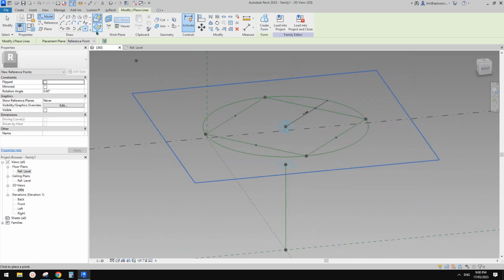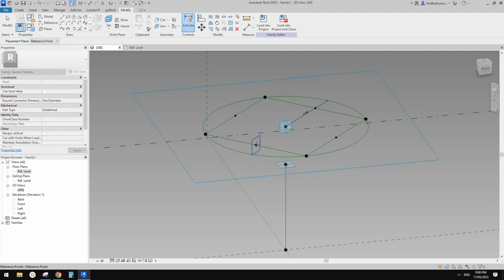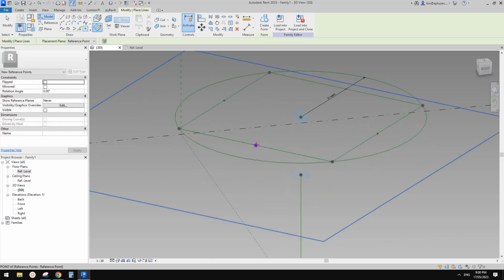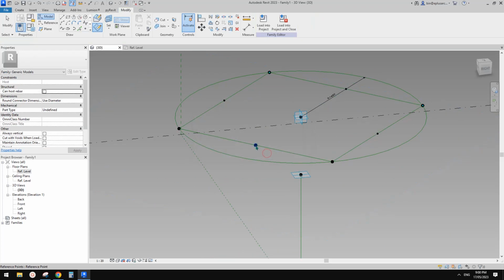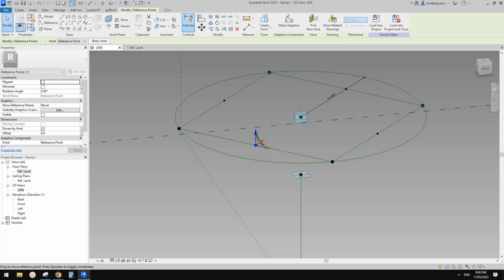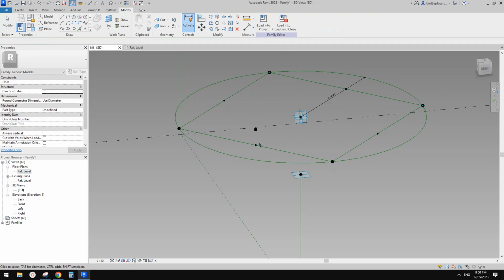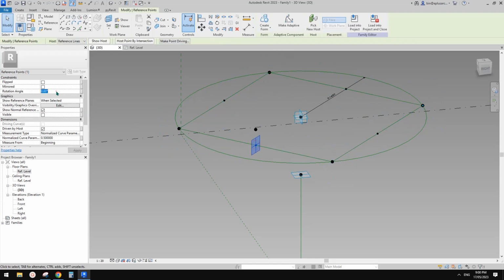offset them. So draw on a point, draw on work plane, set work plane, pick the horizontal work plane. So tab, pick and place. Okay, and select it. Let's just do it. Move it up. We can rotate this. Oh, sorry, Control Z. We can rotate this by 180 degrees, so it will go down.